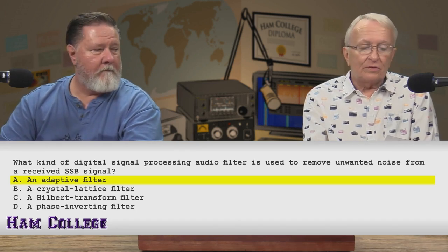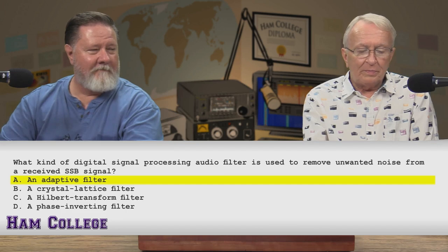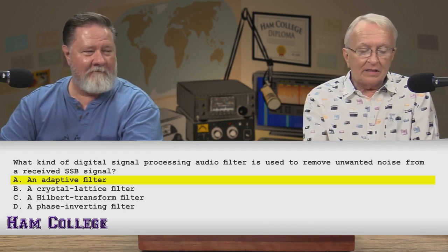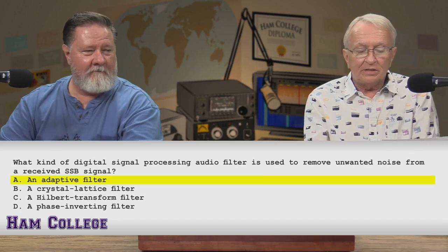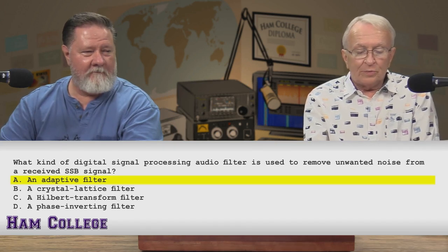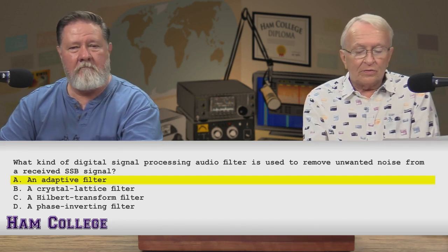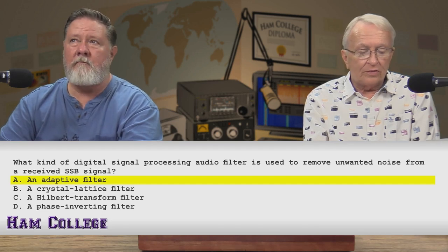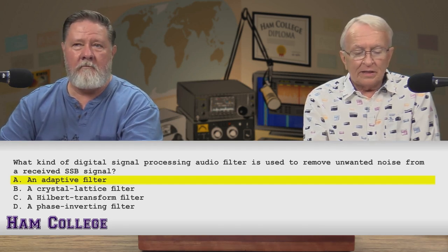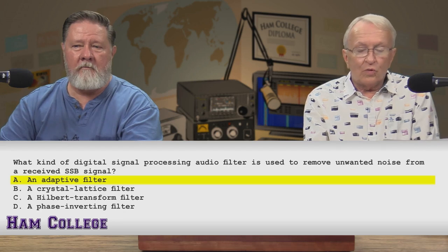The adaptive filter would take input from both the patient and from the mains and be able to track the actual frequency of the noise as it fluctuates and subtract the noise from the recording. Such an adaptive technique generally allows a filter with a smaller rejection range, which means in this case that the quality of the output signal is more accurate.